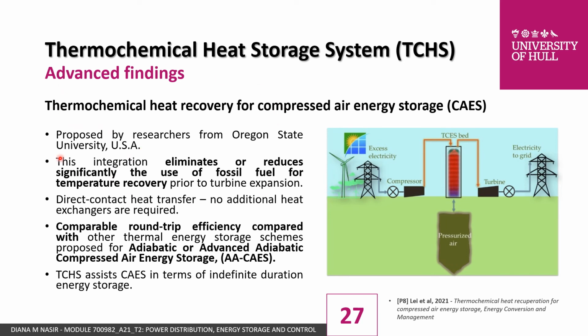Among the new findings on the thermochemical heat storage system is utilizing the thermochemical process as heat recovery for the adiabatic CAES, where this type of storage assists in keeping and releasing the heat or temperature to the air during the pressurization and expansion states. This integration, of course, eliminates the use of fossil fuels, which is a great advantage towards decarbonizing the energy production of the whole CAES system.